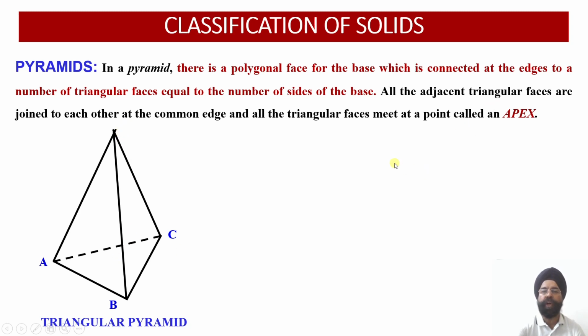So let us first of all work out the axis. In order to work out the axis, from every corner join the opposite side bisector point. So you obtain the midpoint of every side of the triangle and join this with the opposite corner. Wherever these three bisectors join, this provides the location of the axis at the base. Please see, I have drawn the axis. If this point of the axis is O at the top, this point will be called O1. So this is your triangular pyramid.